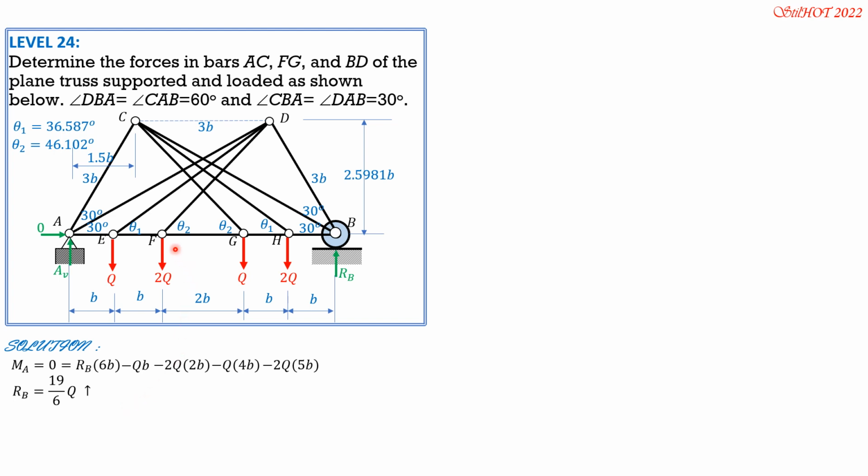Then we begin with joint G to solve for FCG, and we proceed to H to solve for FCH. Then knowing these two forces here, we isolate joint C as a free body diagram because we want FAC and FBC. Take note, FAC and FBC are perpendicular or 90 degrees at C.